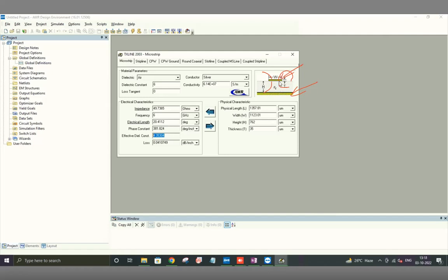Microstrip is sort of like CPWG without the side ground planes, or like the strip line without the top half. These can all be arrived at from different angles. But in terms of making simple sections, if you don't have any components to attach, and you're only making resonators or sections of transmission line, then microstrip is quite a convenient way to do it, because there's only one.